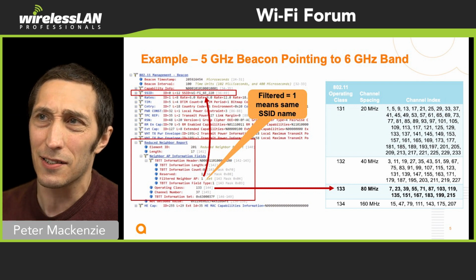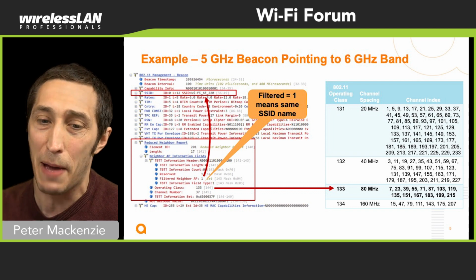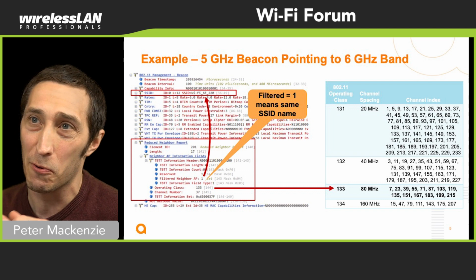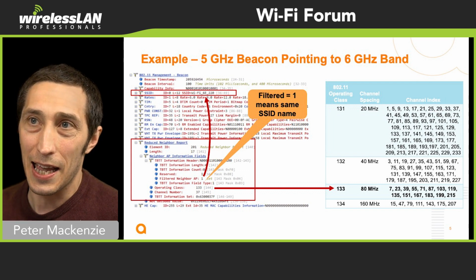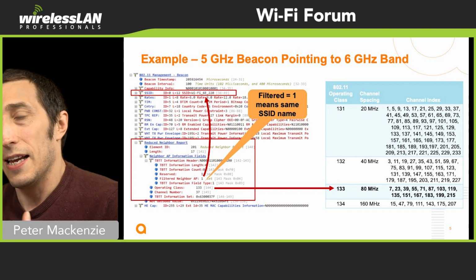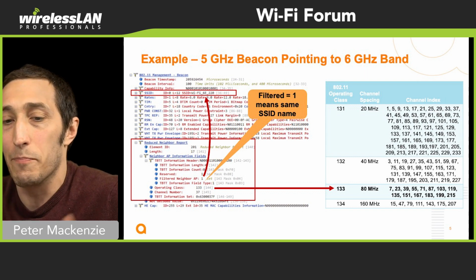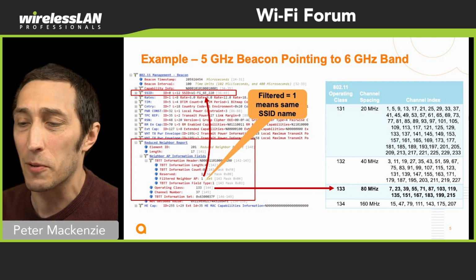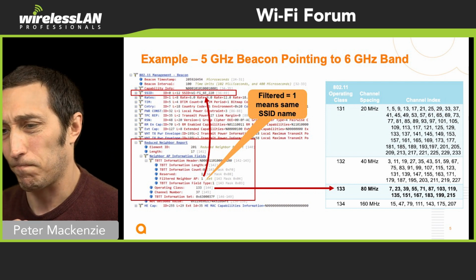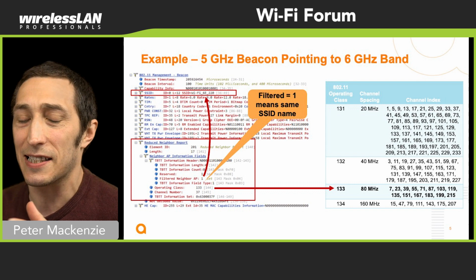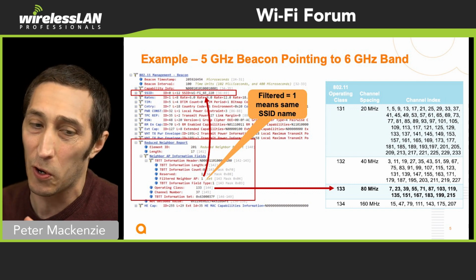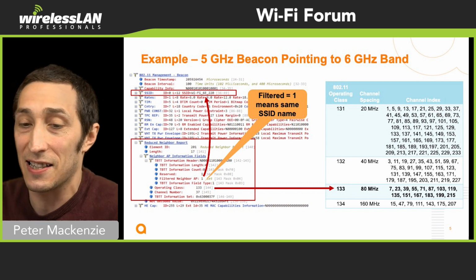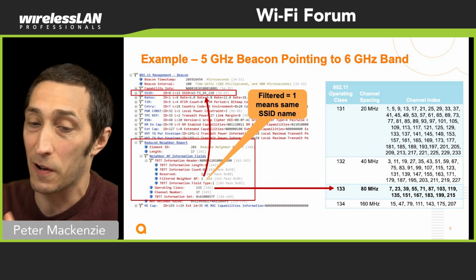And there's going to be what we call in-band AP discovery methods and out-of-band AP discovery methods. So if we're looking at the in-band ones, these are ones where it's possible to actually scan and probe out on the 6 gigahertz band. I think these methods are only going to be used for single 6 gig radio devices. So maybe you've got a tablet and you're tethering it and it's becoming a 6 gigahertz AP. It doesn't have a 2.4 and a 5 gig radio.